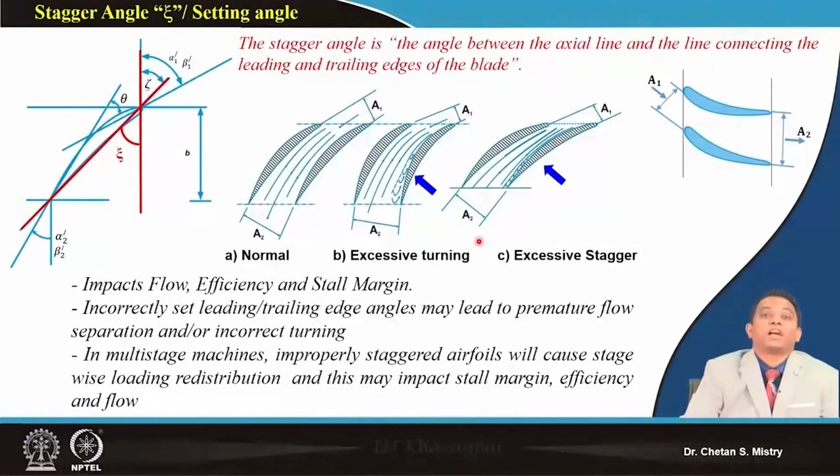If you recall, we were discussing the incorporation of inlet guide vanes. If you consider, my inlet guide vane blades are the same, but we are changing the angle of the inlet guide vanes. When we say we are changing the angle of inlet guide vanes, remember one thing: we are changing our stagger, and that is what manages our mass flow rate. It helps us avoid problems: when we are looking for high mass flow rate, we set our angle accordingly, and when the mass flow rate requirement is lower, we set our angle accordingly. So this stagger angle is what we can arrange. Okay, that is one.